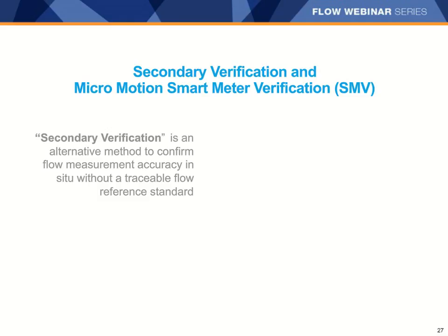Similar techniques that are used with other technologies as secondary verifications would include physical inspection or miking of an orifice plate, spin-down tests on turbine meters, and profile symmetry checking in multipath ultrasonic meters.